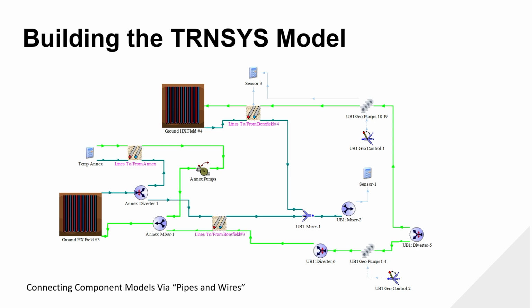And with thermal energy networks, it's really important. I think we've kind of seen how, number one, especially with single pipe systems, what's the temperature profile of that loop? How does each customer get impacted by temperature change across that loop? Is everybody being treated equally? Or are people on the end of the line getting the short end of the stick with efficiencies? What is that efficiency degradation? Is it severe, or is it not a big deal and we don't really need to worry about it? Or where do you plug in those energy resources into that system to keep everything within that balance?